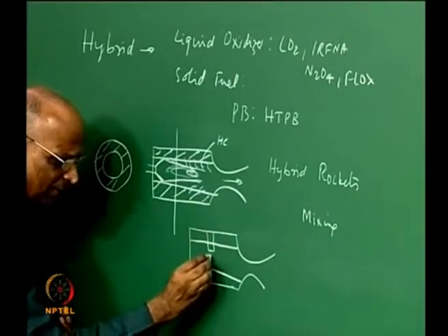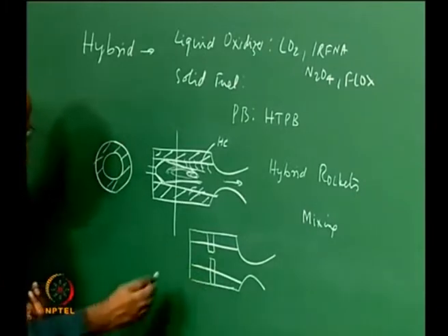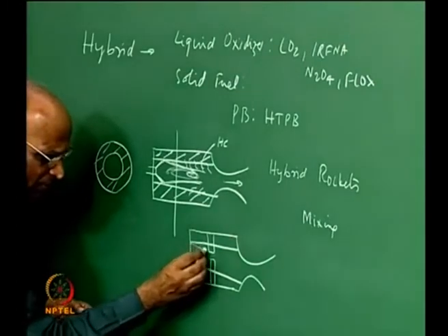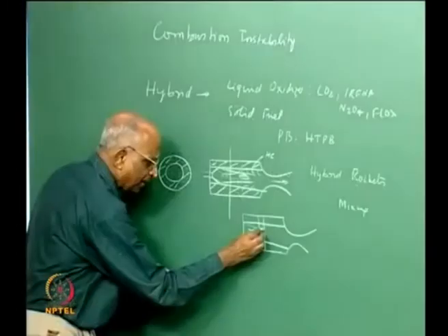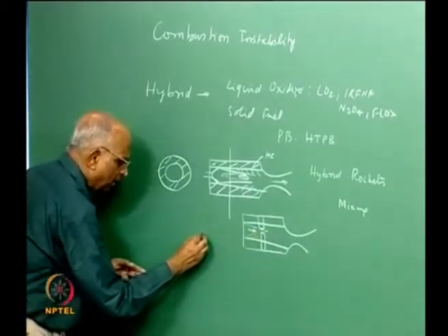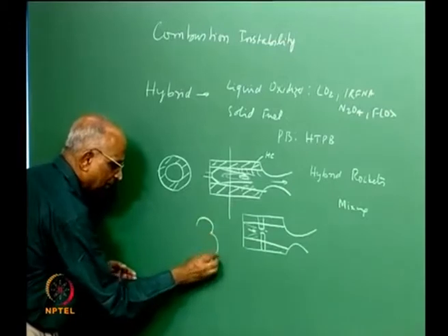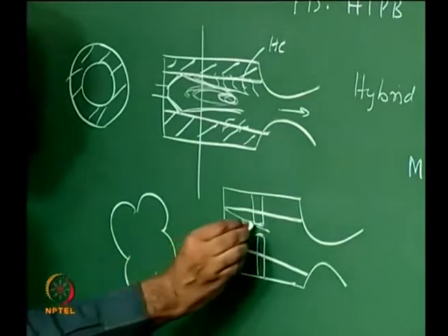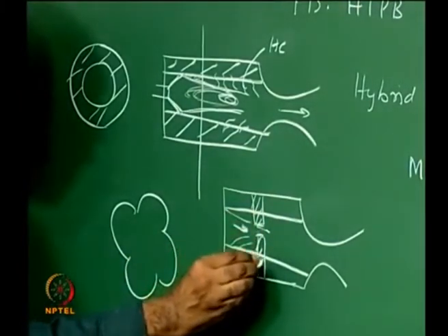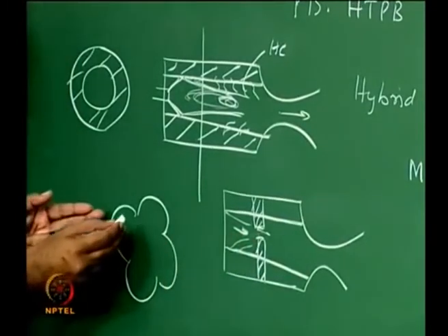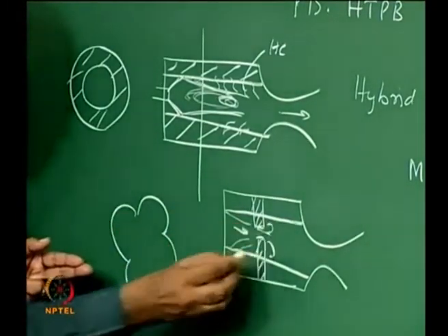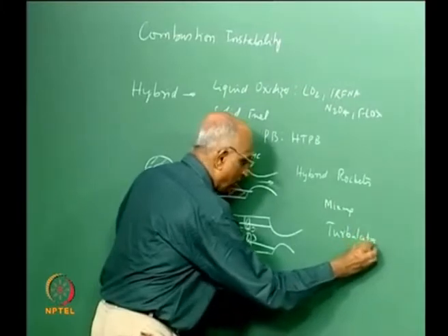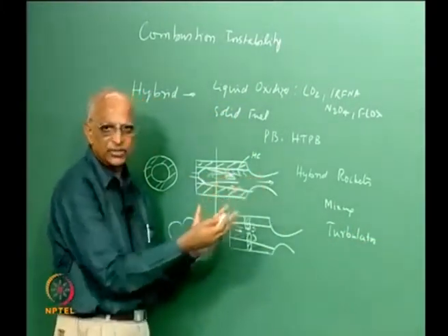What is a turbulator? It is very common in all engineering situations. Fuel is getting evaporated here, oxidizer is coming over here, and I make a constriction over here in the form of, let's say, a petal, something like this. I put this configuration in this hole, and this is a turbulator. When the gas flows across it, it creates eddies and helps to mix, so we need something like a turbulator for mixing the gases so that combustion gets completed.